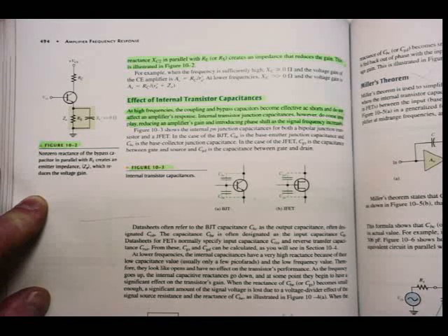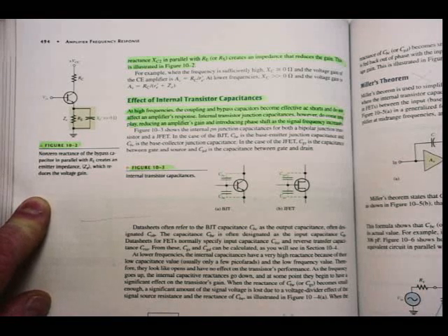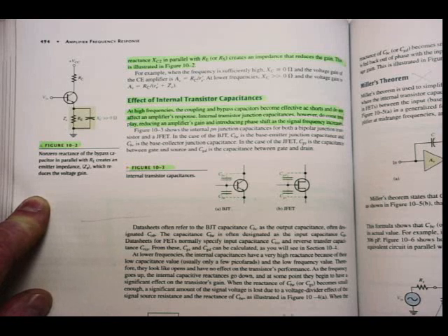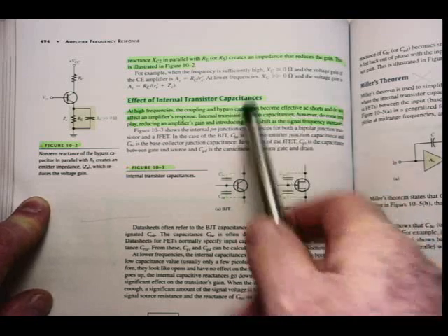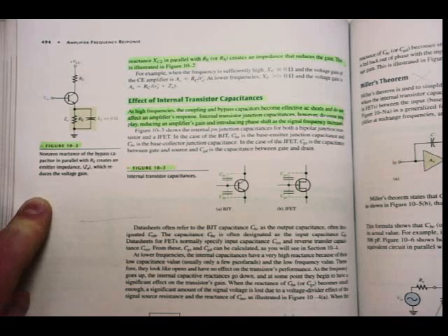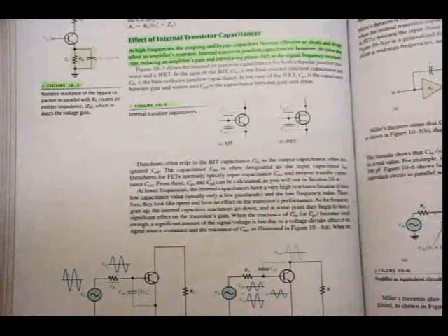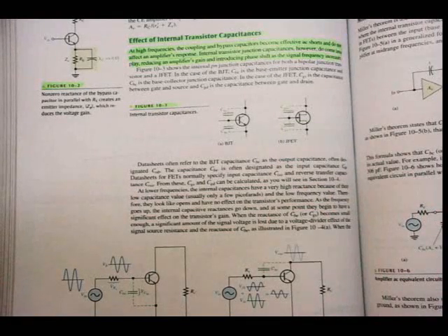So for example, when the frequency is sufficiently high, XC is 0 ohms and the voltage gain of the common emitter amplifier is maximum. Remember, we said we still have to look at the circuit, but it's RC divided by r'e. Everything is bypassed. At lower frequency, XC is much larger than 0 ohms and the voltage gain then has to change to RC divided by RE plus ZE. Just keep that in mind. Alright, that was at the lower frequencies.